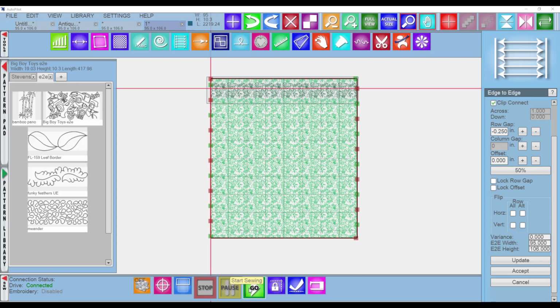So the next three icons are pretty obvious. If I wanted to send my pattern to the machine to begin stitching, I would hit go, and the lightning stitch screen will change and will say continue. When you hit that once, it will move to the beginning of the pattern. You do your pickup, and then you hit continue again, and it begins stitching.